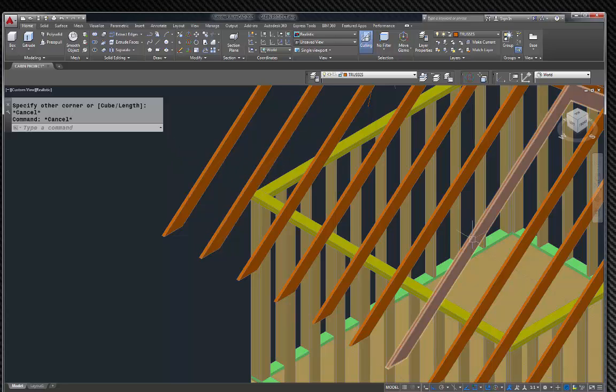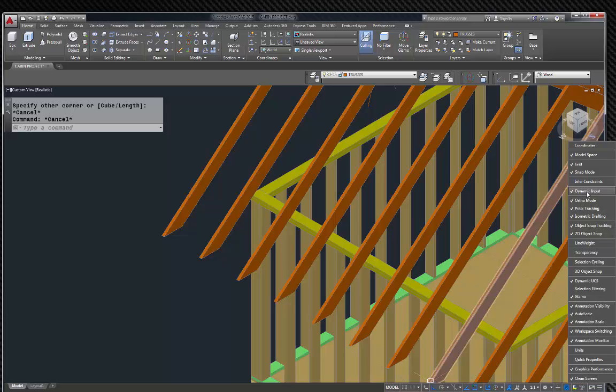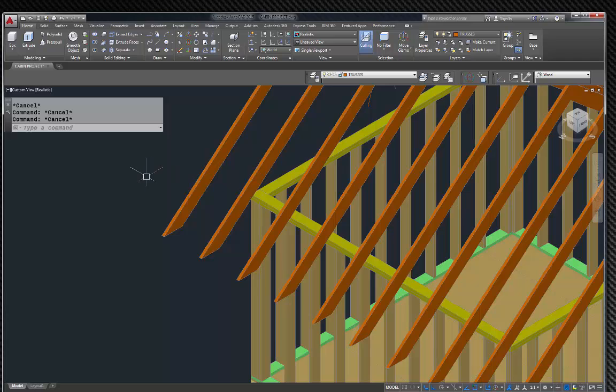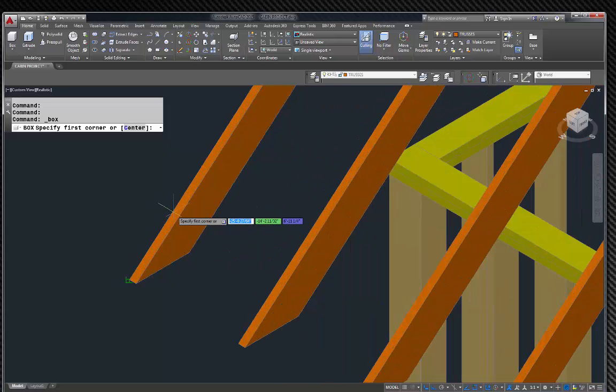And I'm going to go to one of my least favorite things, but I'm going to use it right here, which is dynamic input. Remember dynamic input? If you don't have yours up, go to the 3 horizontal lines here. It says customization, and make sure and check mark the dynamic input. Come over here and turn on dynamic input, and watch what happens with dynamic input when I go to box and I pick this face right there.